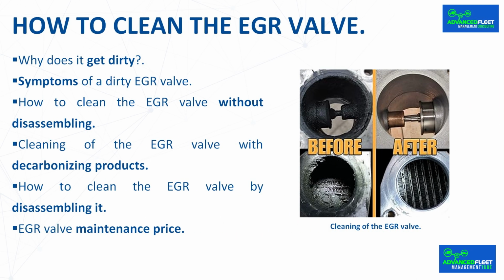2. Deep cleaning. Immerse the valve in gasoline or a specific cleaner for engine components. After several hours, use a brush to remove all soot and accumulated dirt. 3. Reinstallation. Before reinstalling the valve, check and, if necessary, replace the sealing gasket to prevent leaks. Reinstall the valve by following the steps in reverse order.